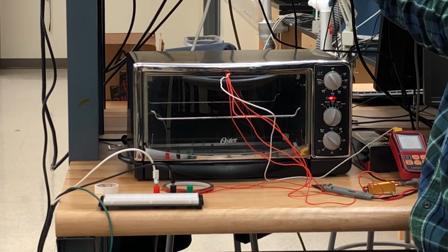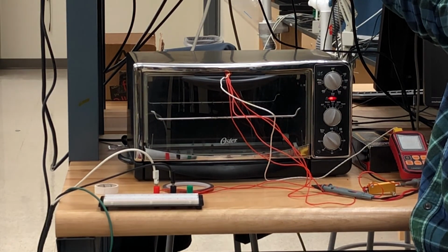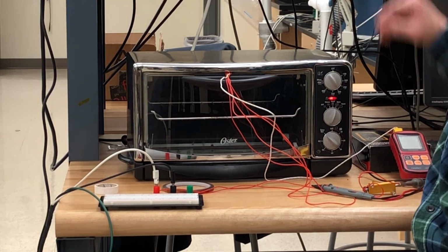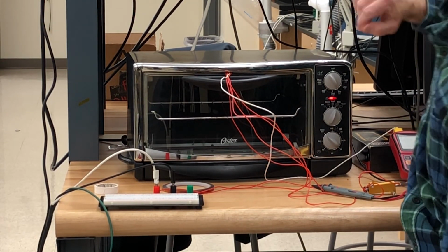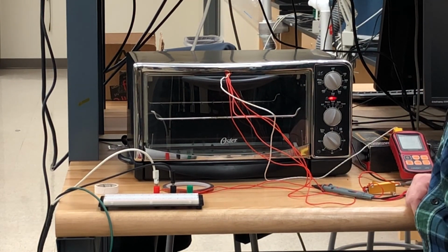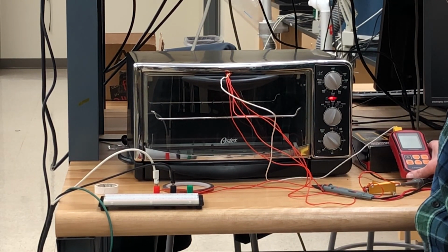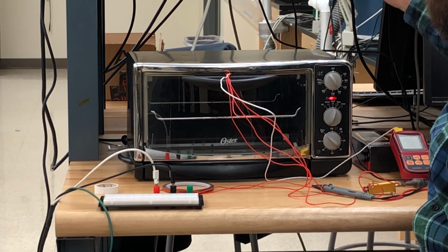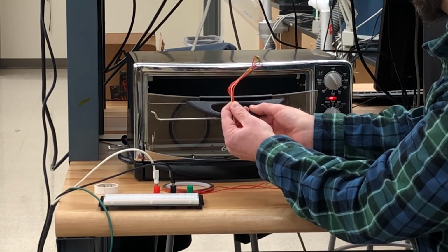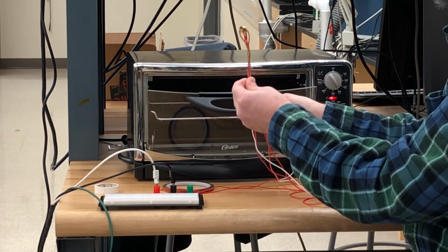It shouldn't be long. Monitor the voltage here. One thing the oscilloscope will do for us is give us an early indication of degradation of the IC chip, and we can see early signs of thermal failure based on distortions that we'll see in the rectified output. So we're adjusting our input voltage. I'm seeing some distortions now, and that's it. We just had failure. It was about 286 degrees Celsius.